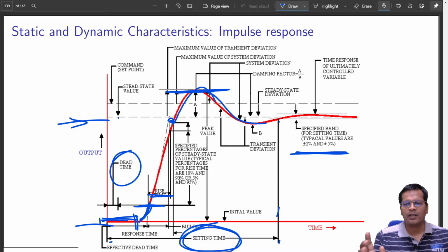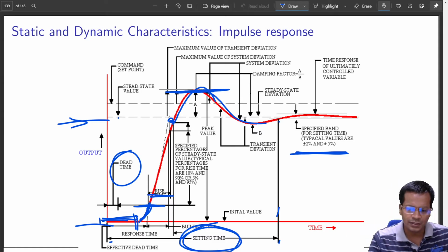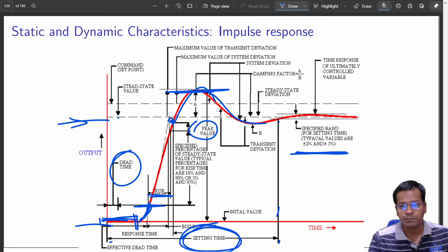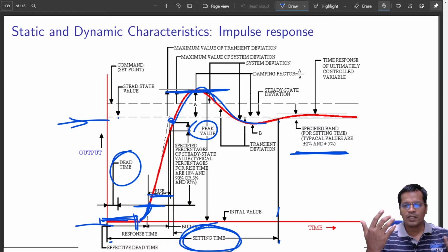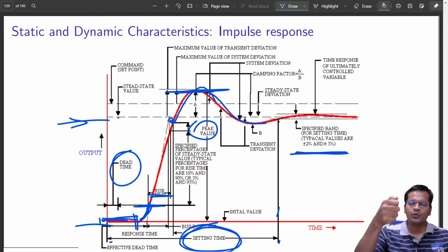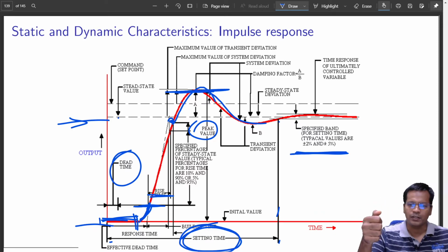And for electrical sensors, these times are very small. You won't even come to know it has responded. But for mechanical sensors, it takes some time, and this is the peak value. How much maximum should I see? In an actuator it is very dangerous at times. I commanded it to go to a certain place, and it has overshot.